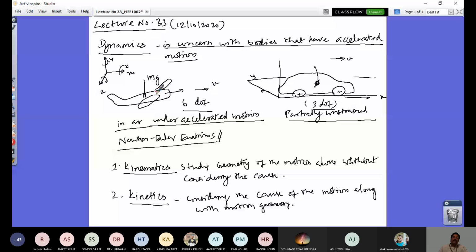In such cases, you look at your dynamics from the ideology we have looked at, called particle ideology. So I call that kind of kinematics particle kinematics. What I mean by particle kinematics is that the physical geometry of the structure is neglected and only the path the aircraft follows in the sky is looked at. The path can be a straight path, a curved path, or a spatial curved path. If that is so, its motion on the path is called only translation. I do not look at the local rotation of this aircraft body, the rotational part, because I neglect the geometry of this aircraft.